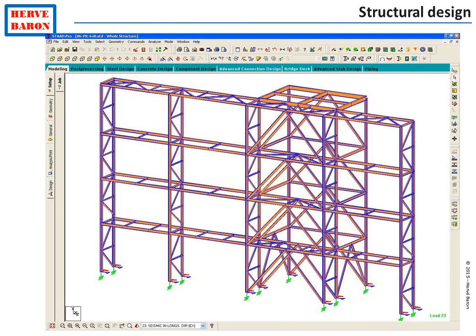Steel structures are designed using a computer software in which the geometry as well as the loads are input. The software calculates the stress level in each member as well as the horizontal and vertical deflection. The steel structure design is accepted once the stress level in each member is safely below the maximum stress level for the selected grade of steel, and once the maximum horizontal and vertical deflections are not exceeded. Then the calculation note as well as the design drawings can be issued.